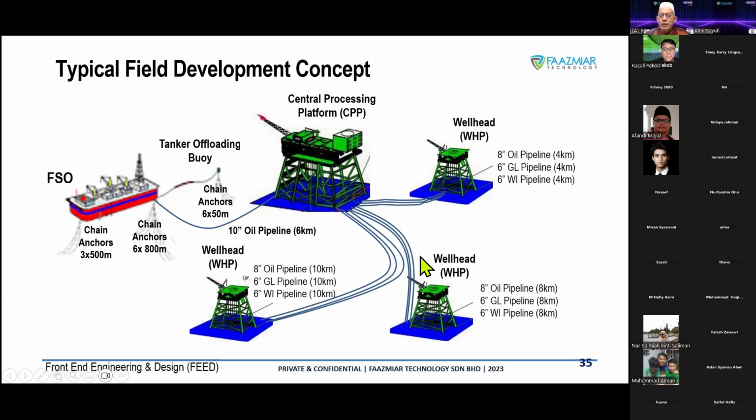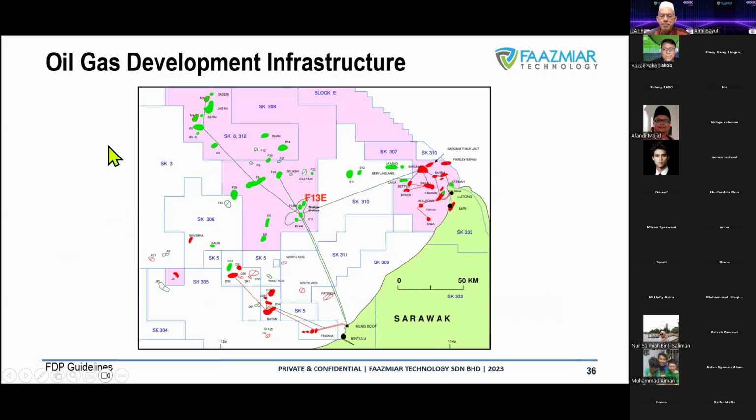If, for example, in some area you have only one wellhead and a small platform, you try not to have too many facilities, only about 30-40% of the function, and then the rest will be done by the floating storage. So if the floating storage becomes an FPSO, floating production, storage and offloading, it depends on strategy. Okay. It's a typical example of sharing.